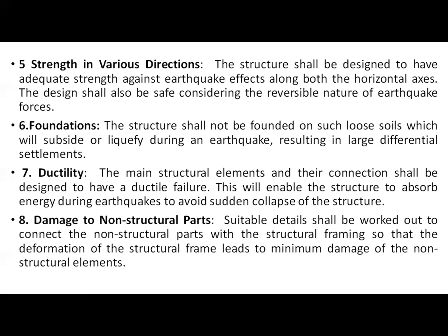and if in that particular area an earthquake occurs because of dynamic loads, because of these seismic waves, what will happen? What will happen because of the seismic wave? Earthquake shaking, so what will happen to the earth crust? Ground shaking will happen. Because of this ground shaking, the water available at the lower depth will be mixed with soil, and because of this excessive shaking, that water will come on the top of the surface of the earth crust in terms of mud.